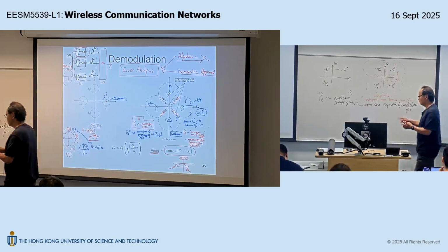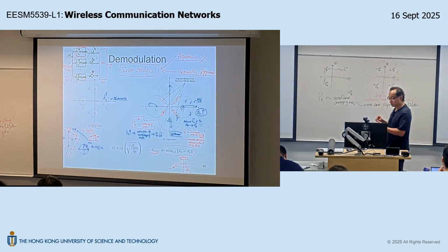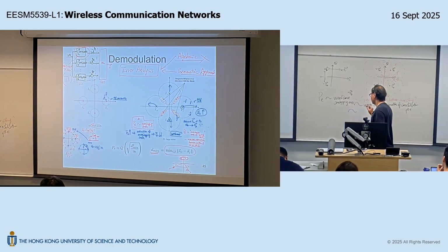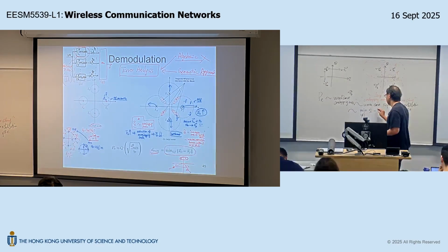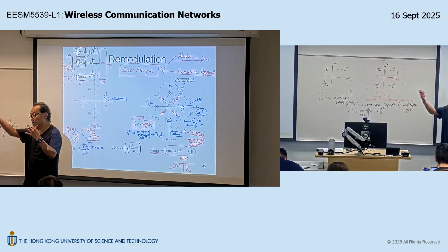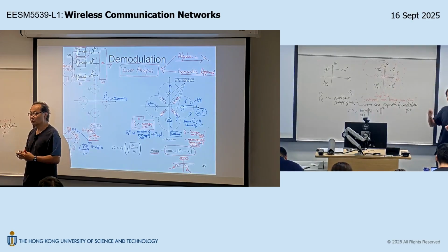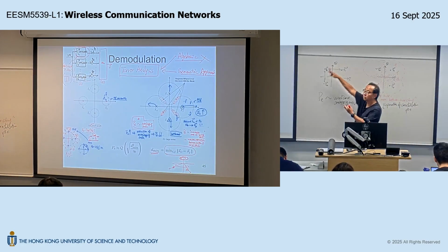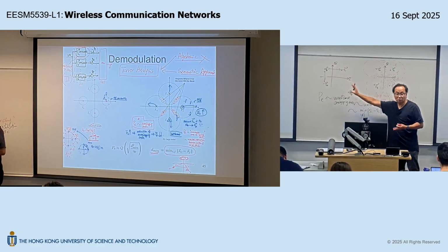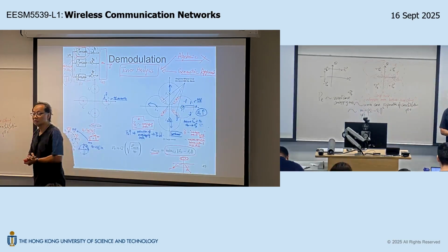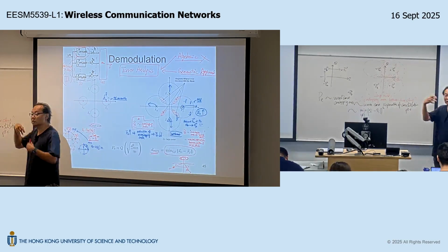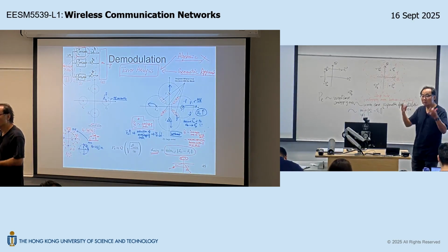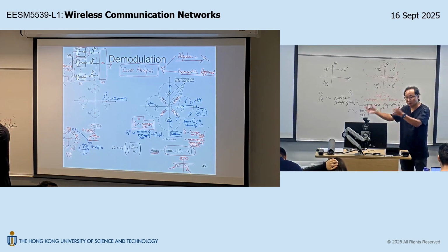So in other words, what's the worst case separation of the constellation points? In other words, it is related to the minimum of the distance between Si and Sj. Si and Sj are any two constellation points. Okay? You compare the distance separation between any two constellation points, and the worst case separation will be your error bottleneck. Is that okay? So if you want to spend some energy to improve the error probability, the energy should be spent to help the bottleneck.